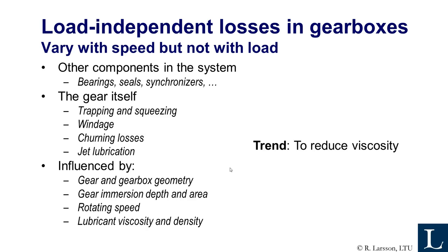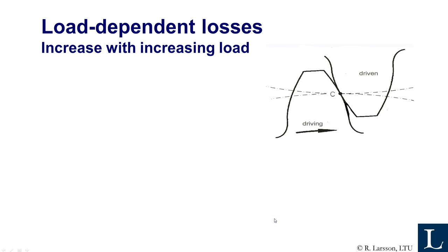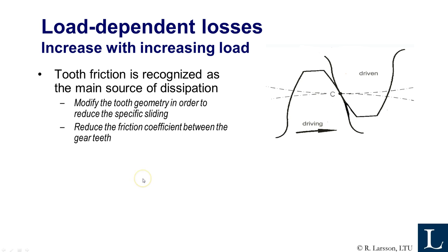So many manufacturers of gearboxes, such as those in the automotive industry, the current trend is to try to reduce the viscosity. That may lead to other problems in other places in the gearbox, such as that you may increase the load dependent losses instead. And the load dependent losses, they are increasing with increasing load, and the main source is of course the contact